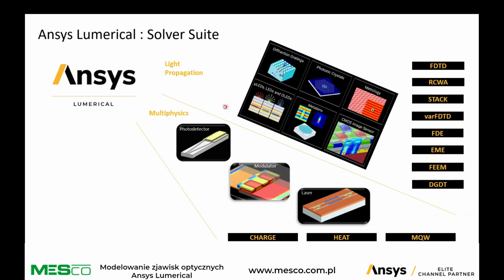And so from the combination of the light absorption and the charge transport simulation, you can extract data like the photocurrents that is generated by this detector. Without any input, you can get the dark currents and so on. So the data exchange between the photonics simulations and the multiphysics simulations is made very easily.